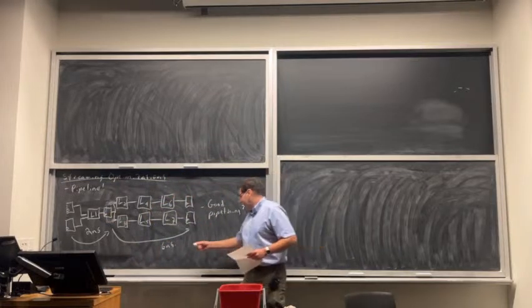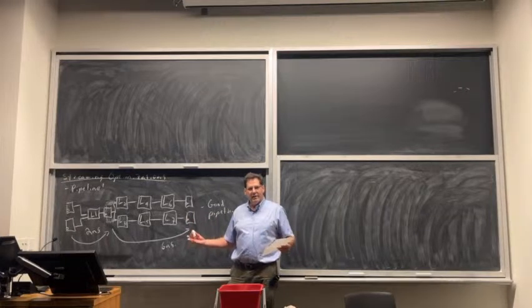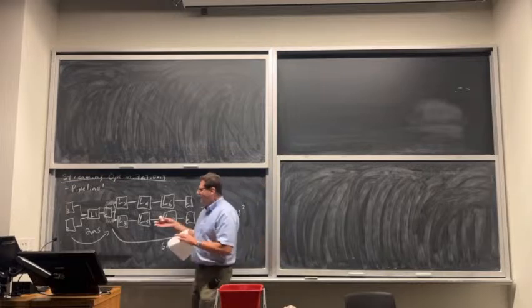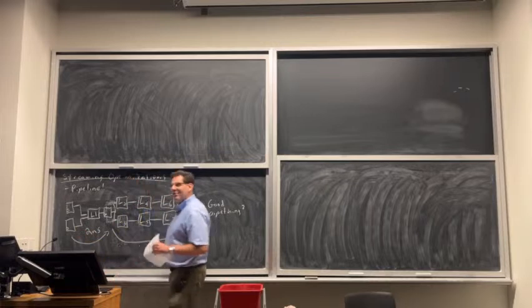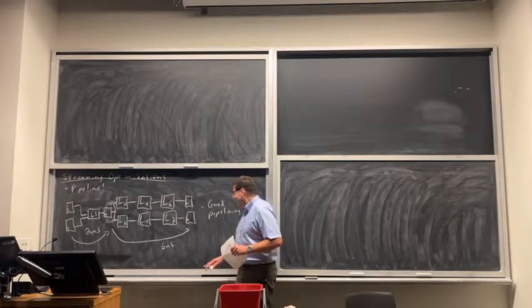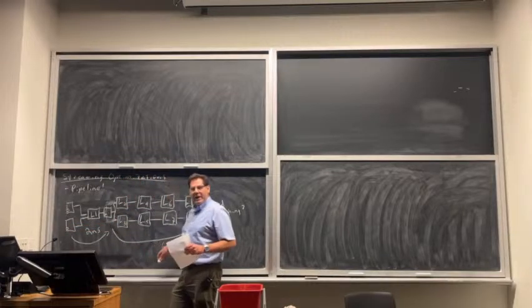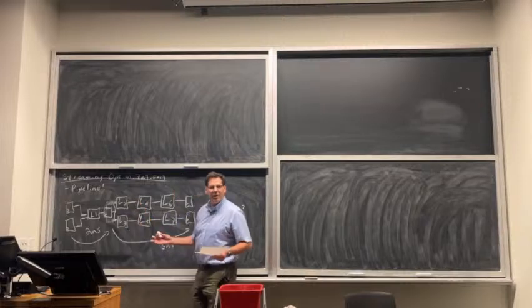So the 6 nanoseconds dominates. That's the longer path. We can't clock this any faster than, well, we need 6 nanoseconds between clock edges. So you invert that, and you get something like 167 megahertz, I think. I should have chosen a number that was easier to invert in my head, which is better than the 1/8 nanosecond clock frequency that we could have had before, but it didn't double.